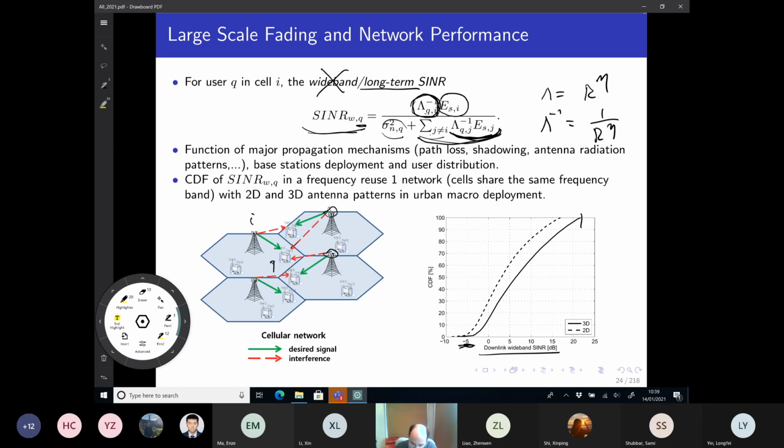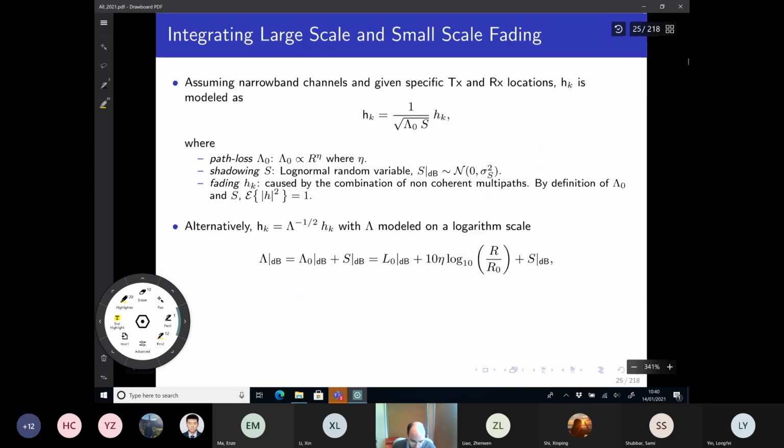Obviously, if you're at 20 dB SINR, you can transmit at a much higher rate. You can receive much higher rates. So the transmitter will probably transmit with large constellations, like 16-QAM, 64-QAM, 128-QAM, or 256-QAM. If you're here at -5 dB, you have very low SINR, so you have very limited rates. You're going to have maybe BPSK, QPSK that are going to have to be heavily encoded as well.